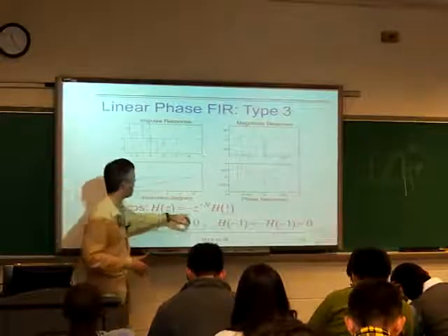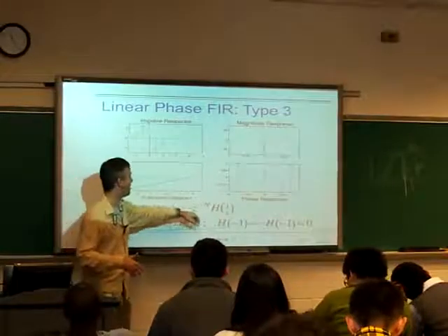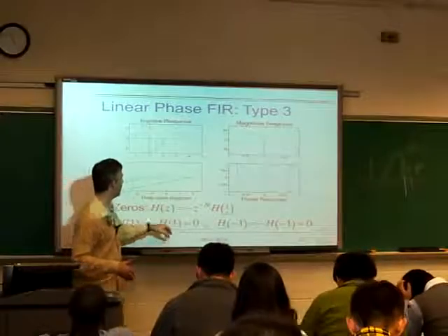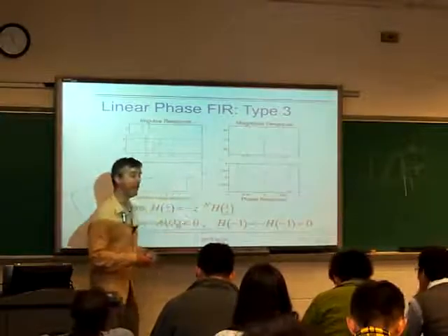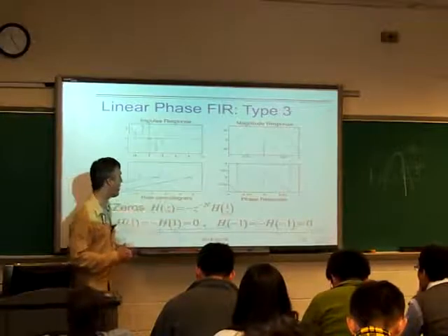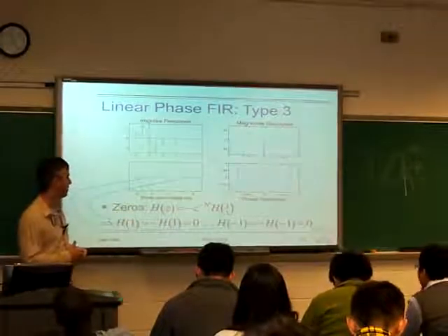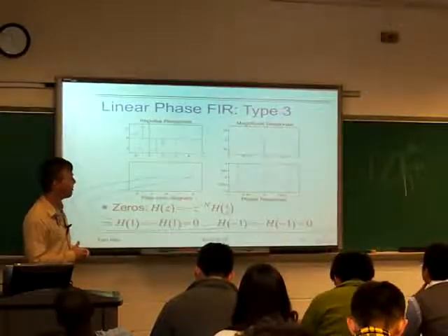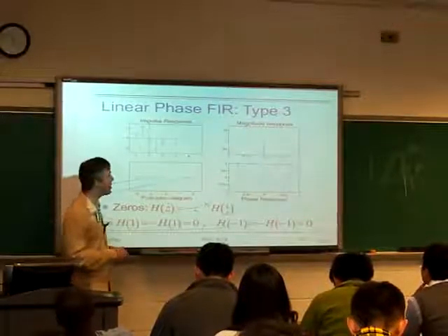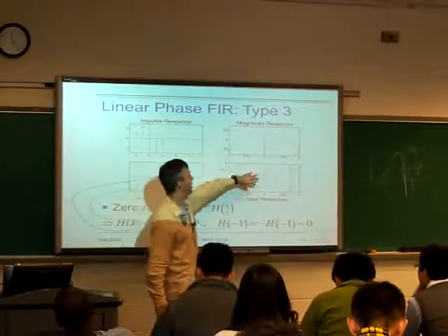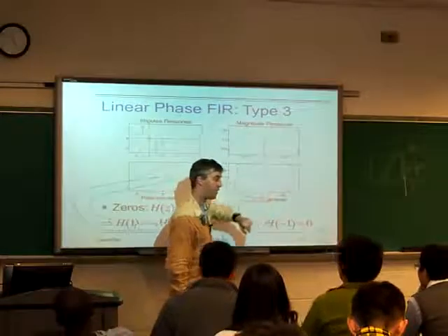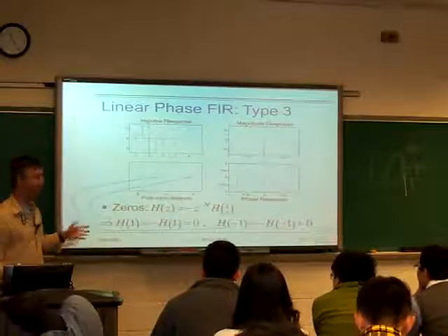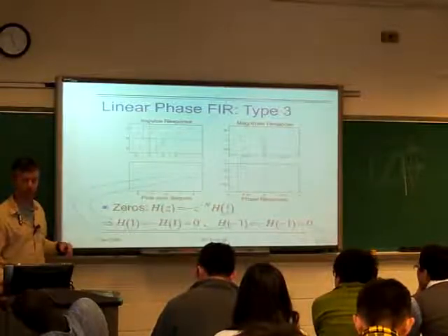Again, if we think about the constraints of the symmetry and the reciprocals, then we get these points that both of these values have to be 0. So we get the 2 zeros emerging just from that consideration. So, like I say, when you use these functions when you want this pi on 2 phase shift, otherwise you'd be much better off with an actual symmetric filter.